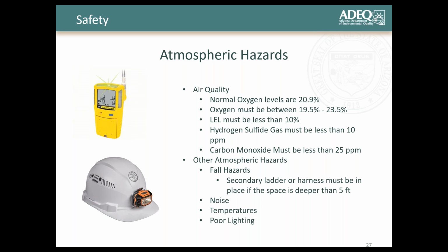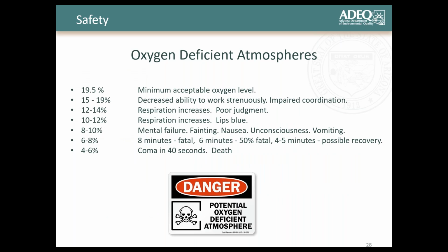Now, coming up next, I want to talk a little more about some of these air quality issues, specifically because collection system operators, I've seen some manholes and lift stations where these things happen often, where your environmental hazards tend to change fairly quickly. I think we mentioned yesterday that the environment of a collection system, especially inside a sewer manhole or a wet well, changes drastically. So you want to be aware of the potential hazards you're dealing with day by day.